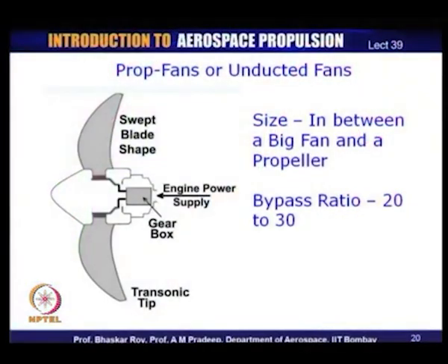The other device we have touched upon is the prop fan, which we have introduced once before. Let us look at it a little more closely. We have seen that the fuel efficiency of an aircraft is enhanced if you introduce bypass devices. Once the bypass is introduced, the specific fuel consumption is vastly improved. This is a known fact for more than half a century, and that is the reason why we have so many turbofan engines.